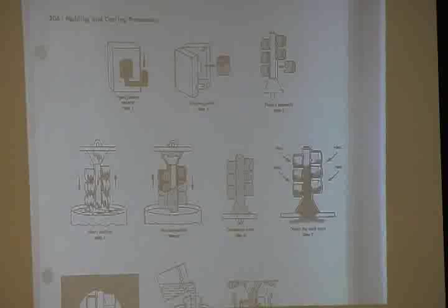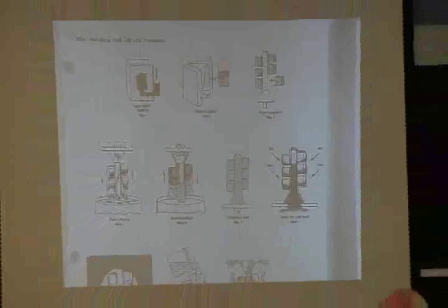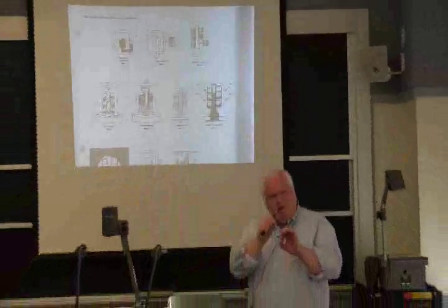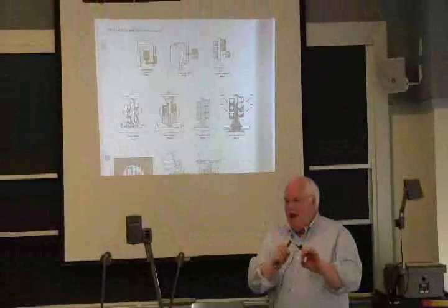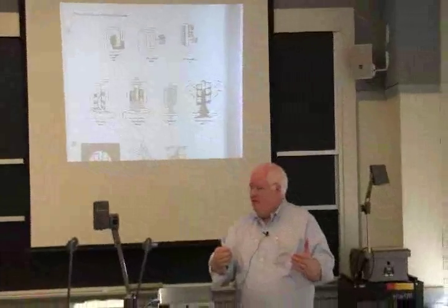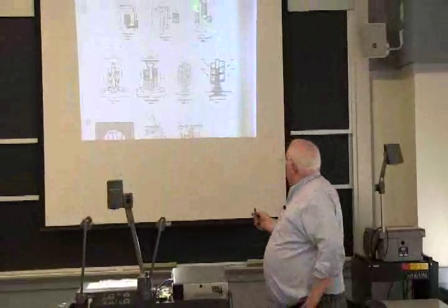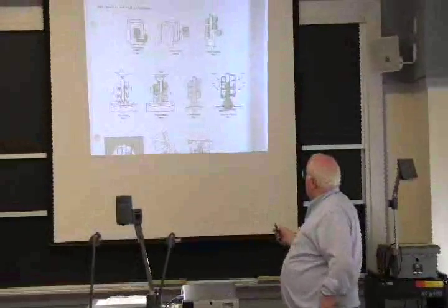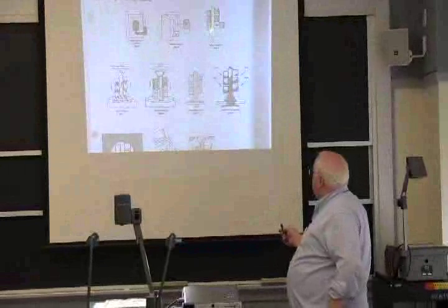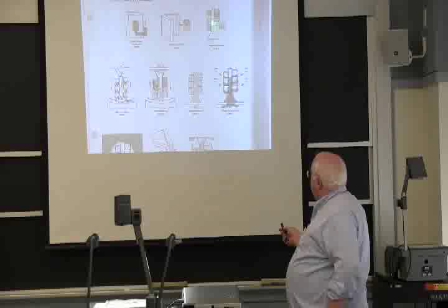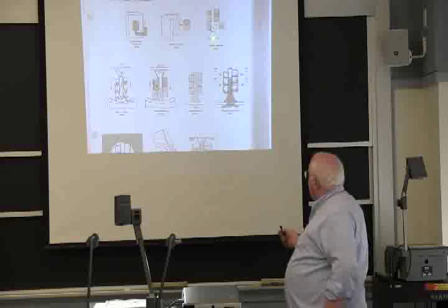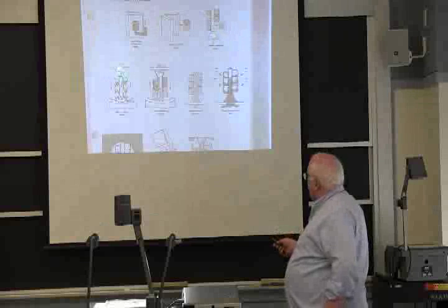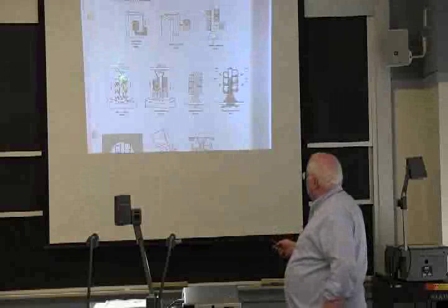You go into one of these shops and you'll see a bunch of women. This is handwork, and women do better with handwork than men. They take little hot knives and they weld with wax, the wax to the wax. They make this little Christmas tree of parts with a riser or sprue, which is where the metal is going to go. This is inverted upside down. You're eventually going to flip it over, and you will pour the metal in this way.